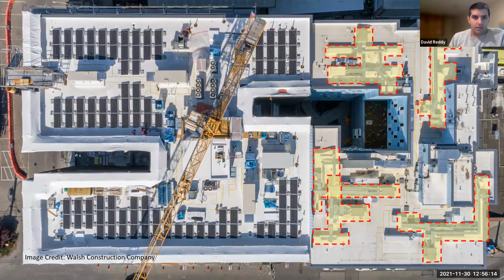Compared to the south phase, which in the end is just 3 rooftop ERVs situated over the corridor in each case. And in this project, the ERVs also ventilate the corridors as well, whereas in the north phase, there's a separate corridor air handler to ventilate the corridor. So it consolidates the number of pieces of equipment in that way.